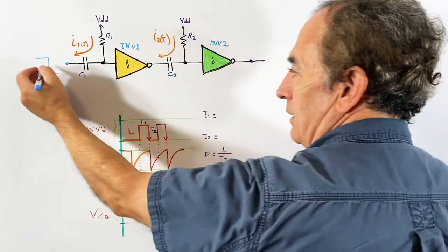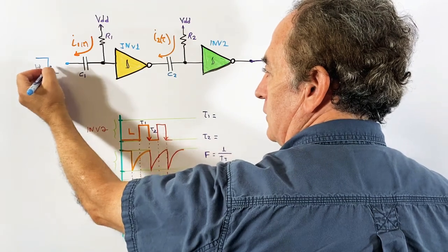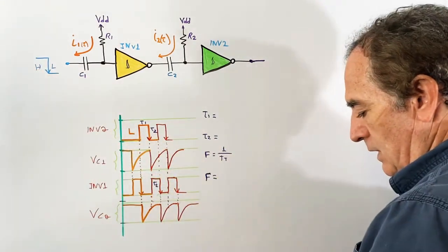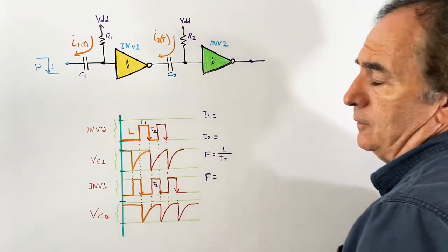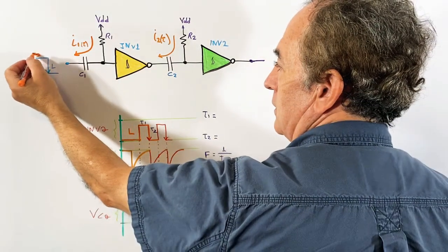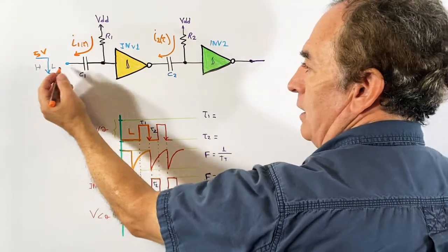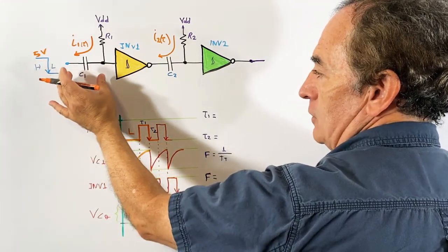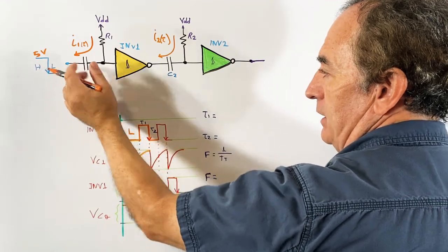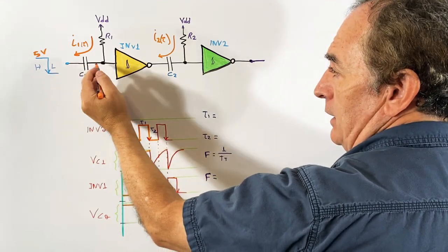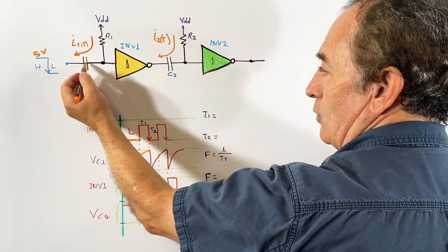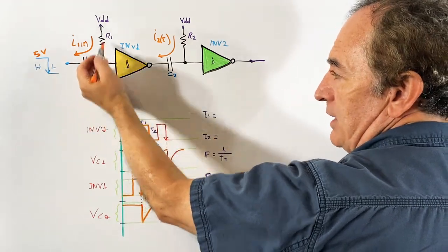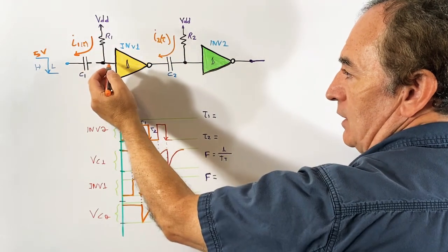So you apply a pulse here from high to low logic at the rising edge. Let's see what happens. When you apply 5 volts first on this pulse, you have 5 volts here and 5 volts, so there's no bias and no voltage, and the capacitor will be open, and because it is open, R1 pulls up the input to a logic high.